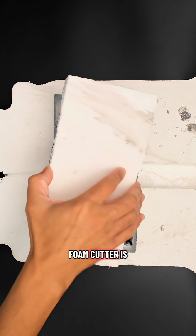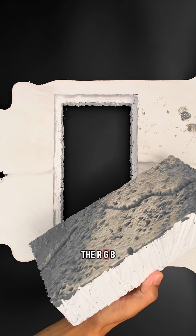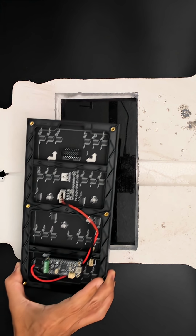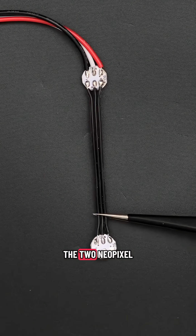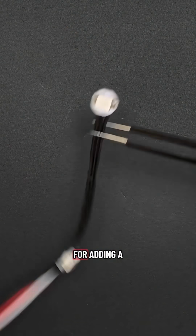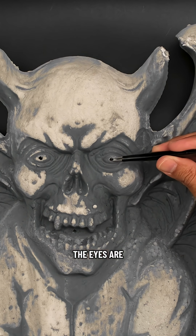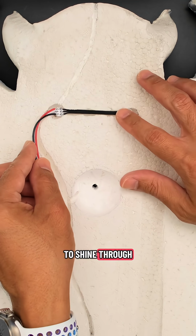A hot wire foam cutter is used to create the opening for the RGB matrix display, and a piece of black LED acrylic diffuses the LEDs. The two neopixel buttons are wired together for adding a glowing effect to the demon atop the tombstone. The eyes are then carved out for the LEDs to shine through.